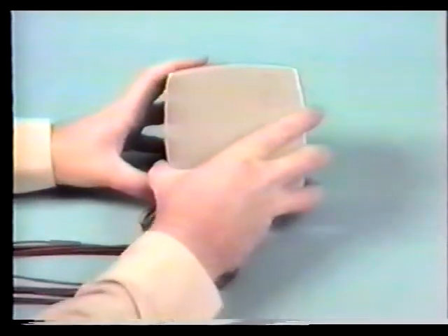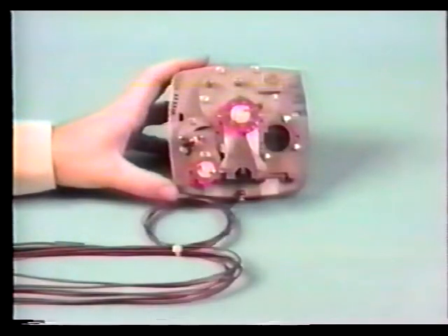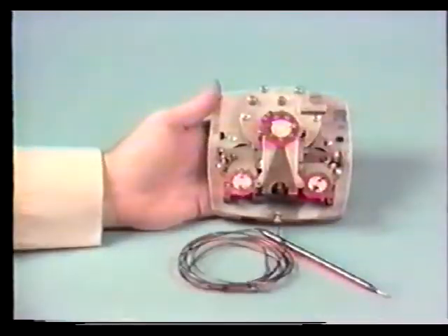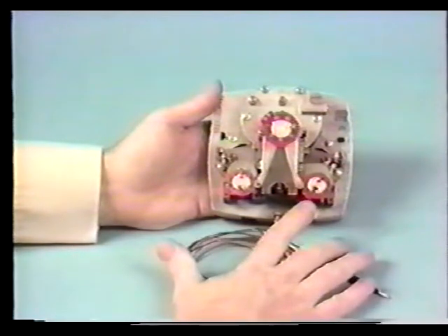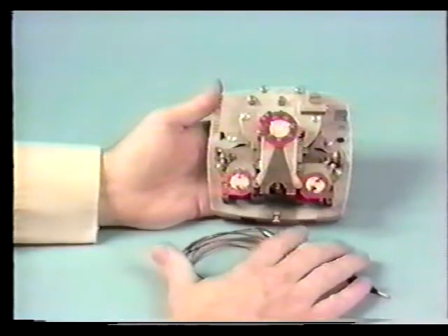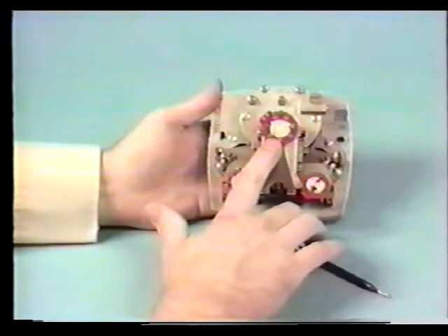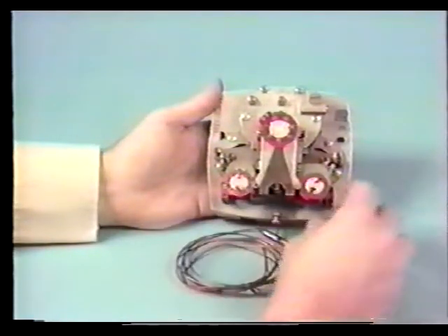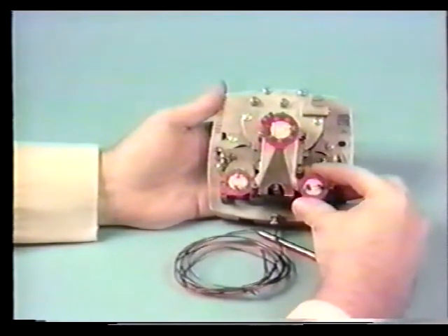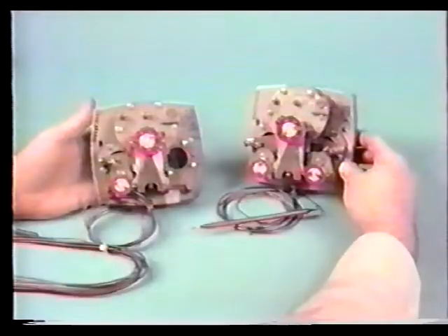Shown here is an example of a remote bulb temperature controller or master controller. And this is an example of a submaster controller, the difference being the addition of a reset scale, which provides the ability to have an input from another controller, which will automatically reset the set point of the submaster controller over a specified range. This is dialed in directly on the controller itself. These master and submaster controllers had to be calibrated separately.